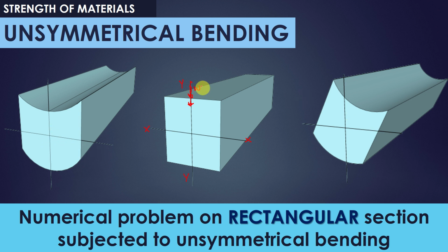And here, imagine the load is acting inclined. The load is not acting along centroidal axis and it is inclined. Then what will happen? The bending profile may be like this. So we have to find out stresses in this type of bending, which is known as unsymmetrical bending for the symmetrical section. Case 1, example 1, rectangular section.